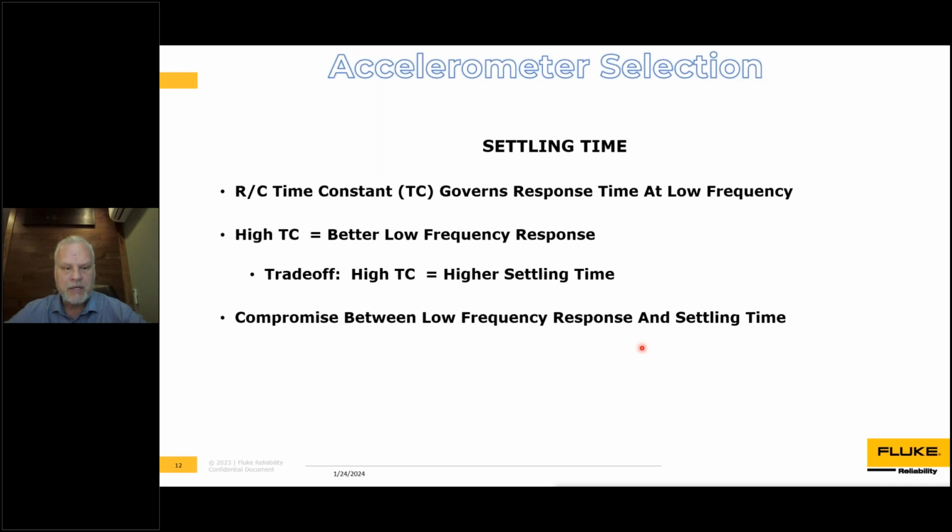Otherwise, you would be standing at the machine for 30 to 50 seconds waiting for that accelerometer to settle. When you attach the accelerometer, it certainly disrupts that signal. Oftentimes it will overrange, and then you have to wait for that sensor to settle out. Anybody that's doing data collection has seen ski slopes and things like that.